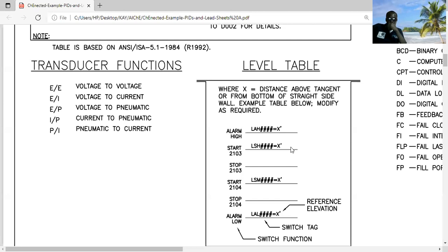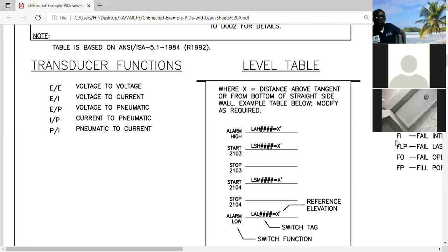When that discharge line is closed, there is no content withdrawing out of the tank. What will now happen? They will give a command to the inlet of the pump, so that the pump will suck more fluid into the tank. So the level will start to build up again, until it reaches what we call the high, based on what you programmed or set the levels to be. If it is high, then what will happen?